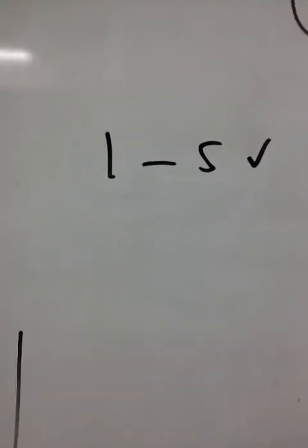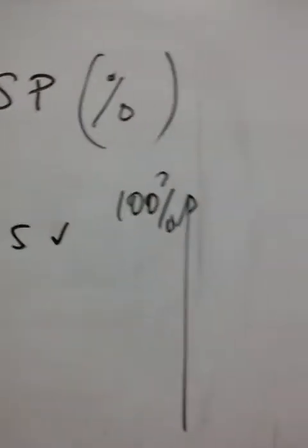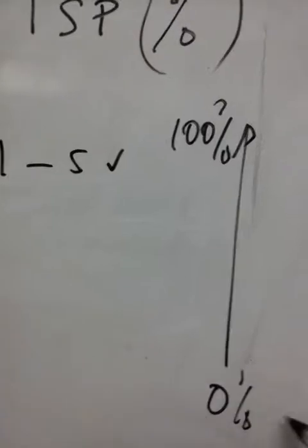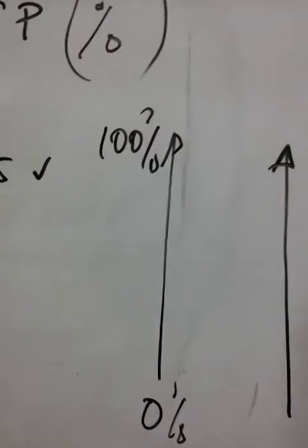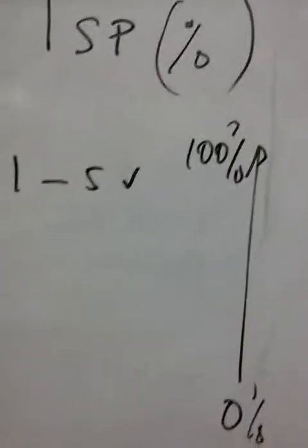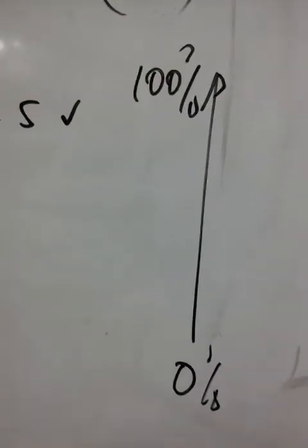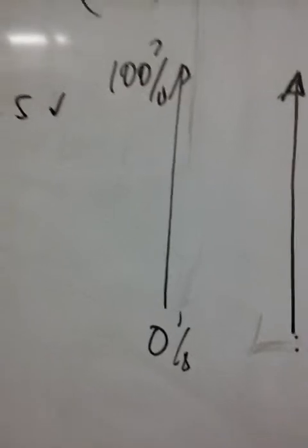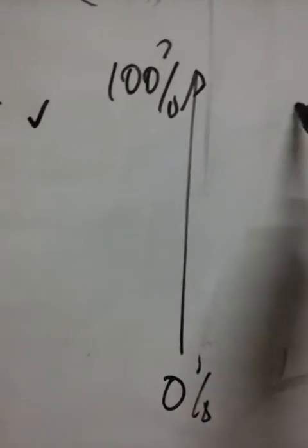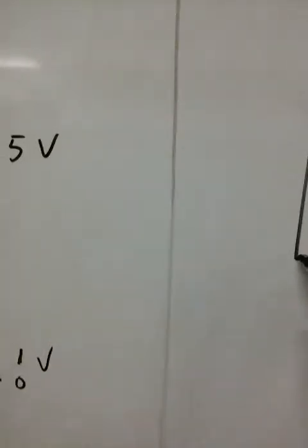Let's say the level changes from 0 to 100%. On the other side, the signal from the sensor will go from 1 to 5 volts. In process interpretation, we don't start at 0, we start at 1, so that if we see 0, we can tell that normally the sensor is faulty. This starts from 1 volt, 1 to 5 volts. Then this is related. It's a linear process.